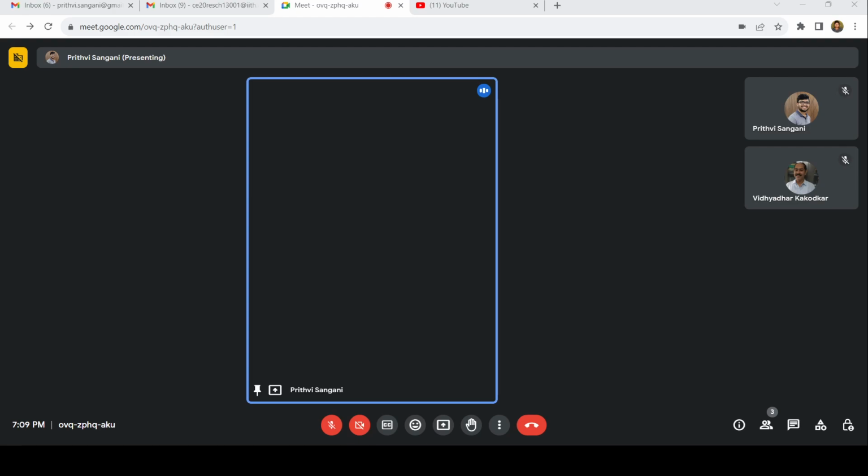Now what is happening for ui? ui is nothing but the internal forces. So minus 1 by root 2, 1 by root 2, 1 by root 2, 1 by root 2, right? And 1. So we have only 5 forces. So what I'll write is minus 1 by root 2 for AB, BC is 0, CD is also 0, minus 1 by root 2, minus 1 by root 2, AE is also minus 1 by root 2, BE is actually 1, AD it's also 1, positive.